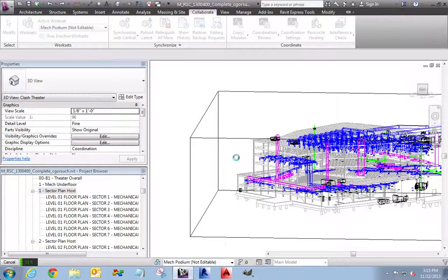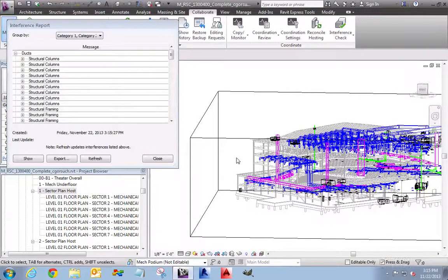This is actually pretty good at what it does, but Revit will clash against what's called a hard collision, which means that these objects are actually going to have to intersect each other, even if it's by a minute amount, just a fraction of an inch, which in most cases is easily correctable in the field. They have to actually touch or intersect.